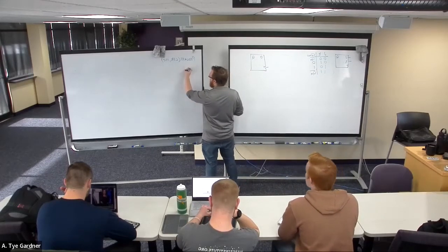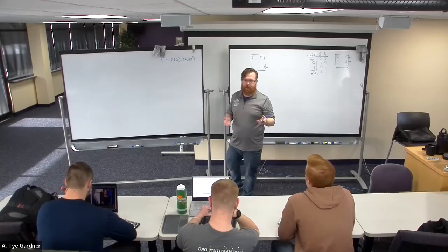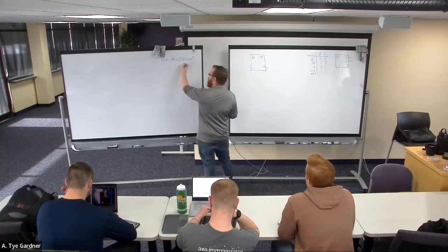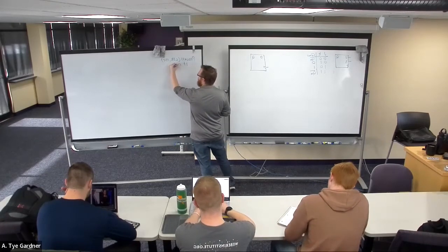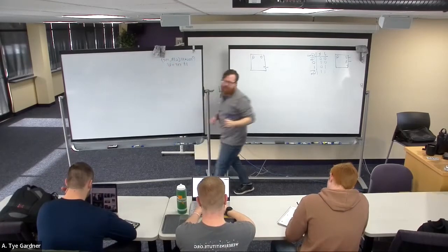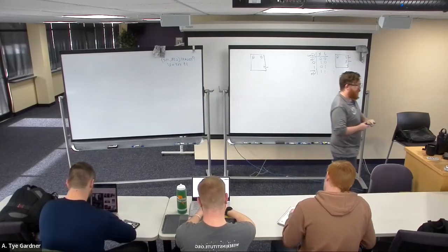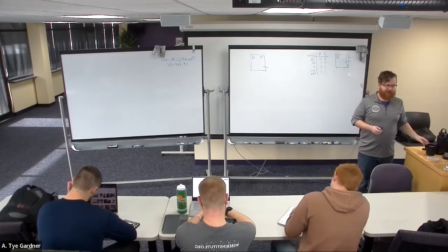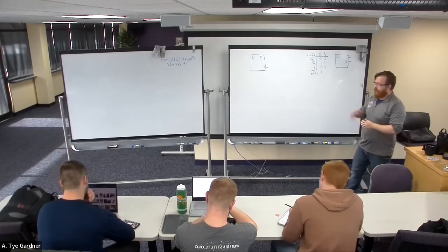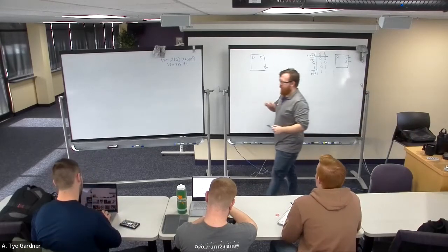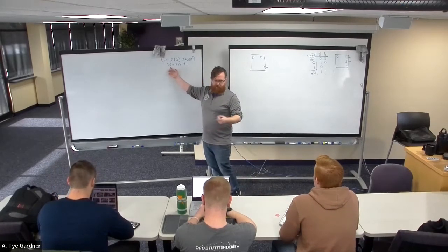Then what we're going to do is basically if statements. It's just conditionals. It's just asking questions. And the first question I want with an asynchronous reset is if reset equals 0. Now this makes it an active low reset. 0 is reset. Always be careful to make sure that the reset is what you think it is, and it's good to be consistent across your designs for the moment. You will run into designs that have kind of mixed resets, which are really annoying to deal with, and I don't ever do it that way, but it could. So this is saying if reset goes to 0, let's reset.